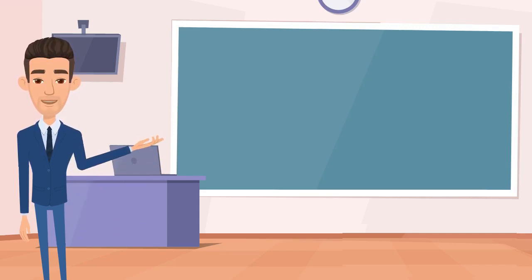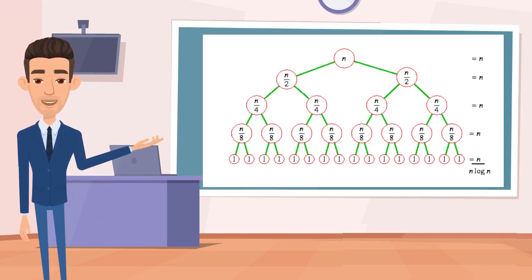This efficiency is achieved by exploiting the symmetry and periodicity properties of the discrete Fourier transform. The FFT algorithm begins by dividing the DFT computation of a sequence of N points into two separate computations of N/2 points, which in our case are the even and the odd. This division is performed recursively until reaching base cases, typically when the sequence length is a power of 2.